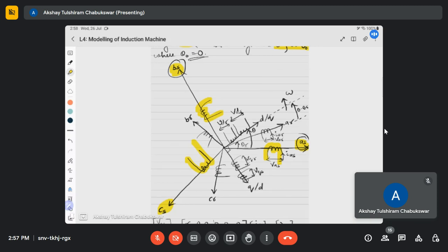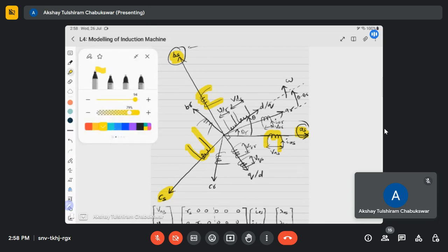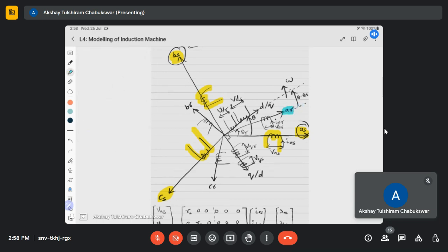The rotor of an induction motor also has distributed conductors, where the conductors are short circuited. Similarly, we can draw three vectors. Here you can see the stator is in yellow color and the rotor I will show in light blue color: AR, BR, and CR. As you know, the electrical quantities of the stator are leading with respect to the rotor because it is being excited. Because of this stator excitation, and the interaction between the stator and rotor magnetic fields, some electromagnetic torque will be produced.